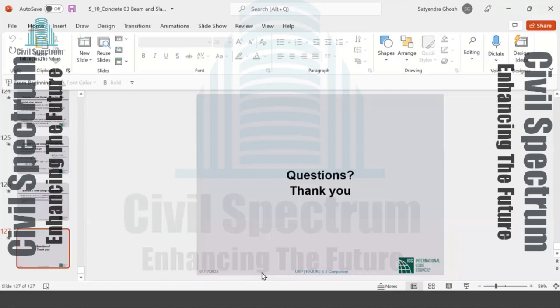The diagonal shear rebar, horizontal and vertical shear rebar, and the flexure rebar all together create such a congestion that concrete pouring becomes difficult. Yes, I agree. So you have to be very mindful at the design stage.